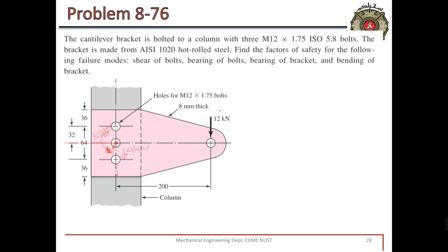Then we have the equation, for example, to calculate FA double prime, the equation of ratios of R's. So it is M RA divided by RA square plus RB square plus RC square.